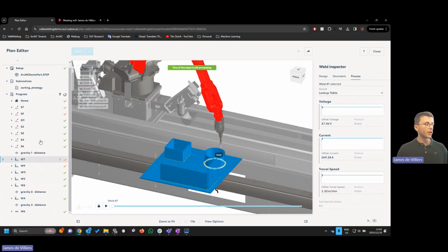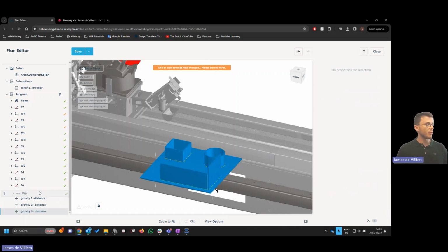If you want to touch and weld every weld, you can of course drag like this to do touch and welding. So it's very simple here to change to touch and welding if your heart so desires. Then we won't be using these gravity groupings like you see here. But now, of course, if you're going to do touch and welding, you will know that it's important to cut your wire. Every time you weld, your wire is going to melt back, and then you cannot touch sense with your wire tip. So at this stage, it's important to put in what's called a subroutine.